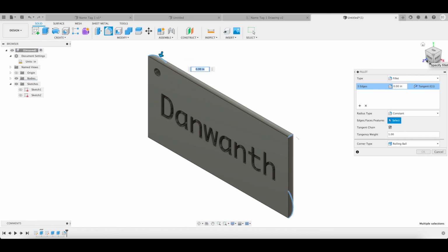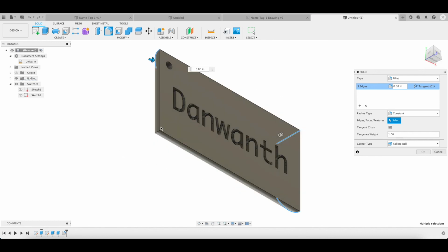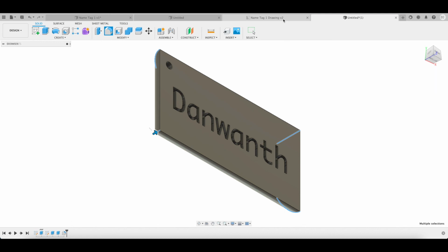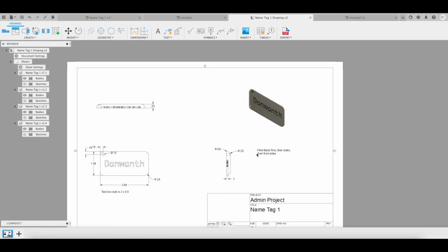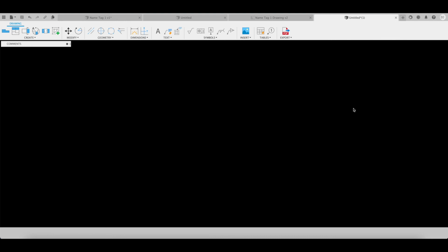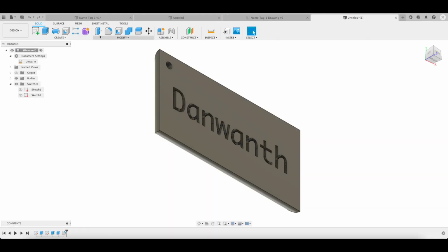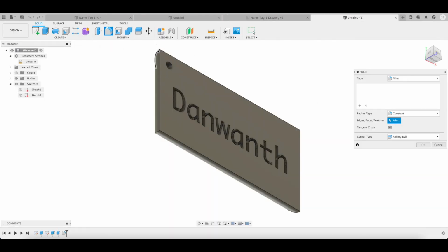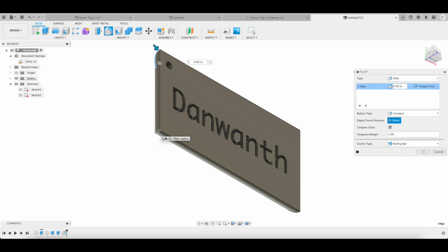We'll go to the other side, select the last edge. And this, if I recall, which I don't recall anything, we'll see this. What is this? The fillet radius is 0.25. And I'm going to have to go back to the fillet tool again and select all the edges. And you can have already entered 0.25.